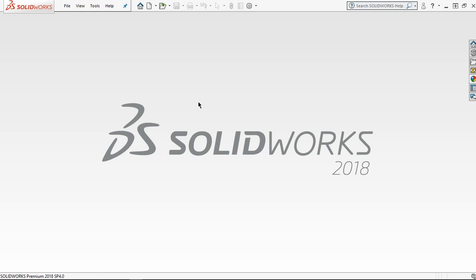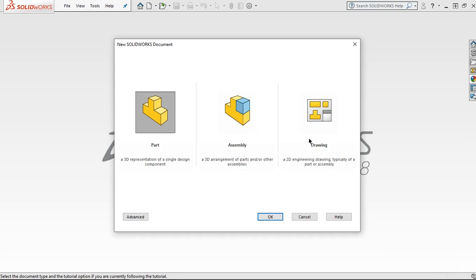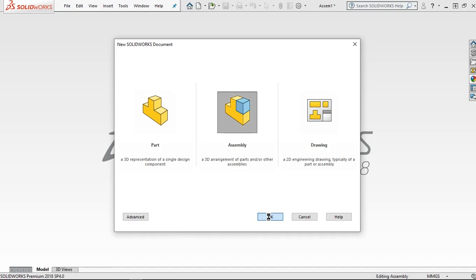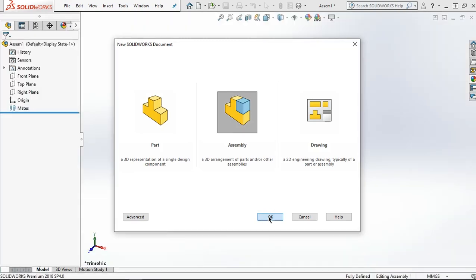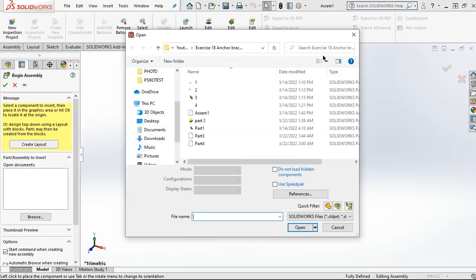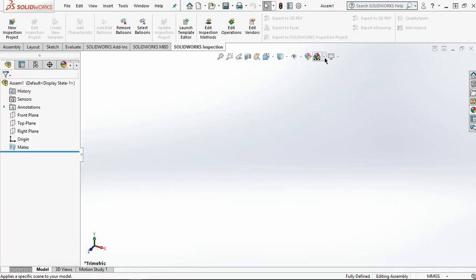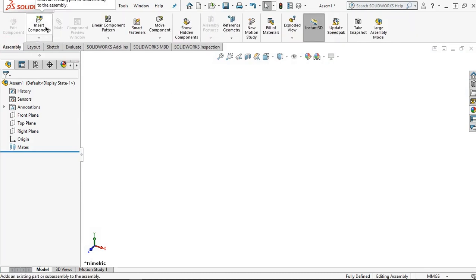Hey guys, this is the assembly session from this video, and I want to start from the file and click on new and select the assembly. For the first one, I want to change the background and make it plain white and make the assembly by clicking insert component.